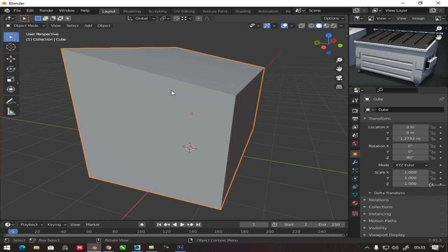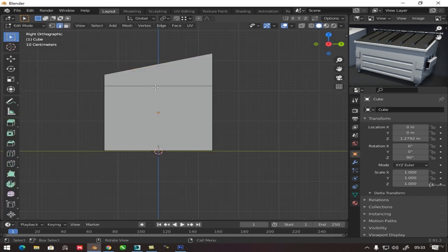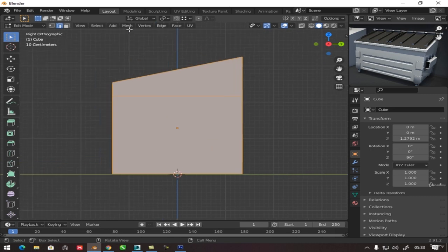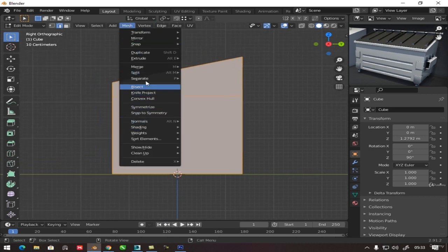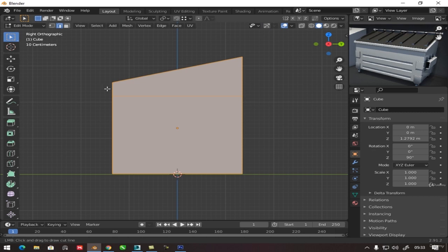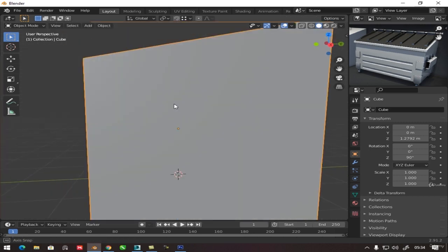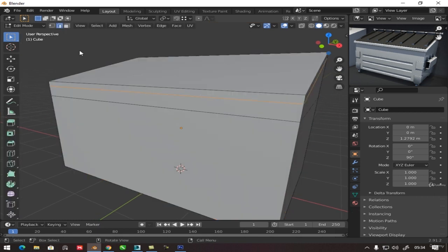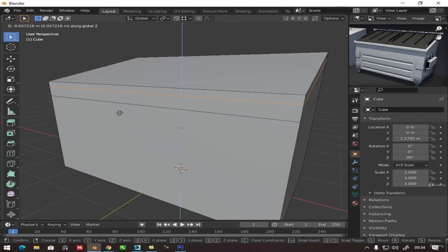The idea was to come very correct, but it didn't, so I will solve it with Ctrl plus, and I'll do like this. I'll put in the lateral view. I'll select everything with the A. I come to my mesh, bisect, and I will trace from here to here. And in here, visually, it's the best way to keep a position that it's equidistant. In case it's not, I can come to the rotation, the position, and adjust in the way that I want according to my need, okay?